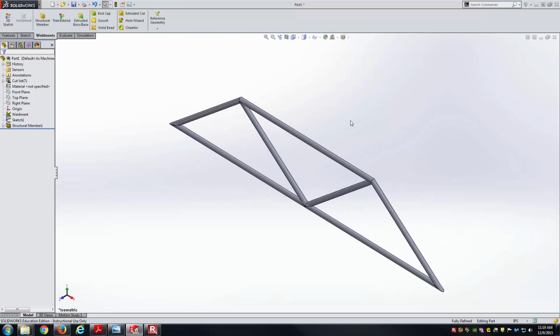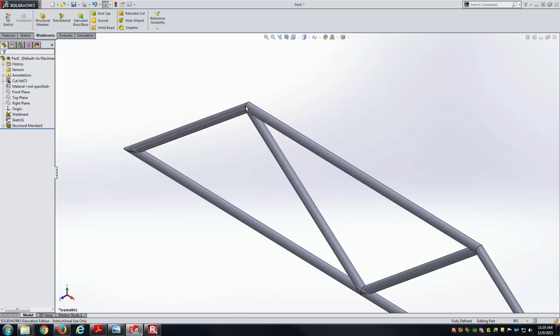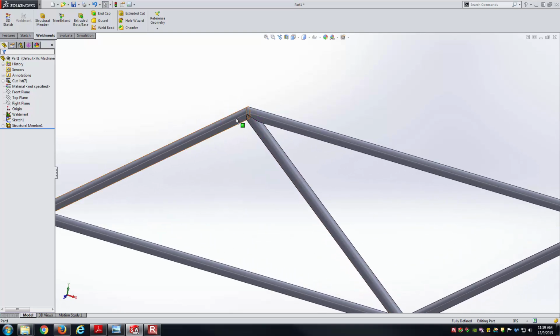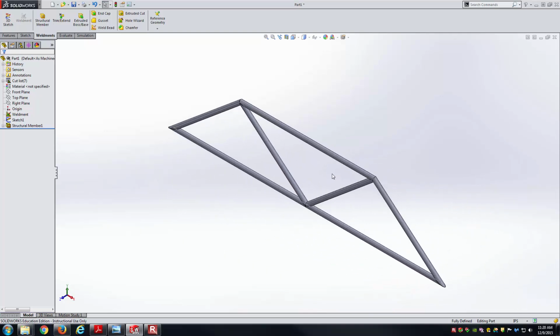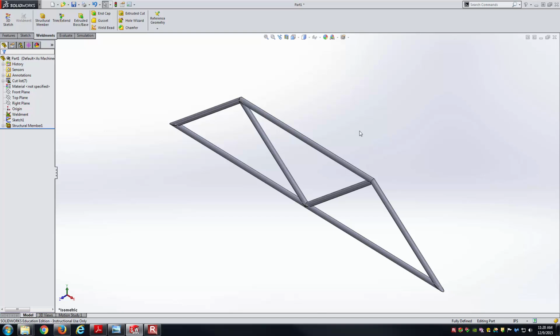And so at that point I've got the truss geometry here. What has happened is basically we've applied that 1.25-inch Schedule 40 steel pipe profile, or cross section, to each of these individual members. And so that's basically it for the CAD modeling side of this problem. We've got our geometry defined, and we also defined the cross sections associated with the overall truss geometry.